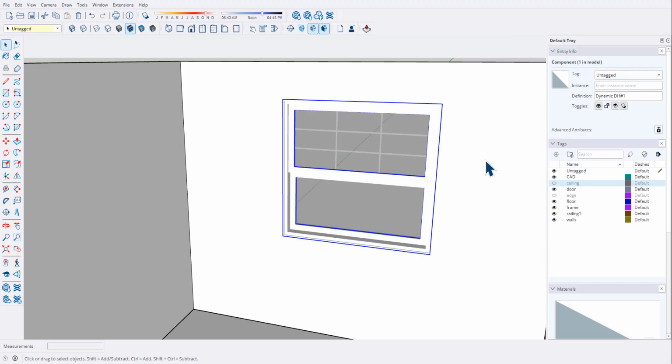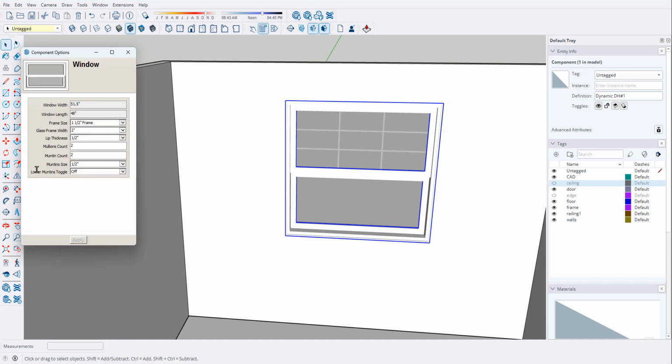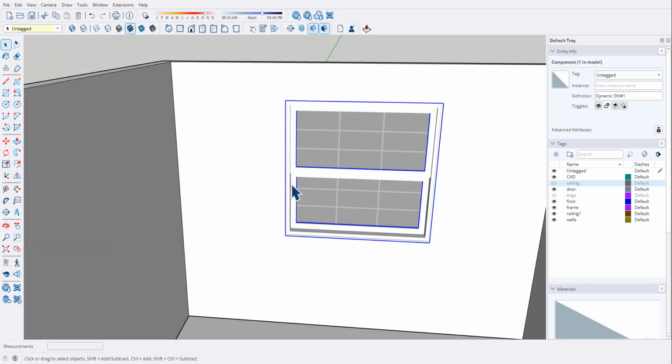So we're saying this is either a single hung or double hung window, but it's a single one. And then I go to this properties here, and because I've selected this, I can say if there are mullions there, and right now there will be, so I'm going to do on for the bottom mullions. Click apply, and now we've got mullions top and bottom. Otherwise, just say 0 or whatever number it needs to be.